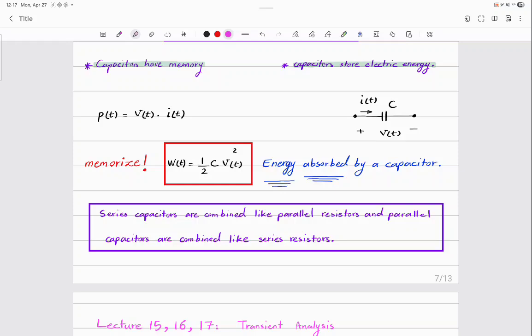What do you calculate in the second step? Whatever quantity the question is asking, okay? You should focus on whatever quantity is asked. What is step 3? Infinity. What are the things that you can do to the circuit to simplify for t equals infinity? Short for inductors, open for capacitors. Why? Because the circuit is not changing anymore, okay? Everything is in DC form, it's not changing.